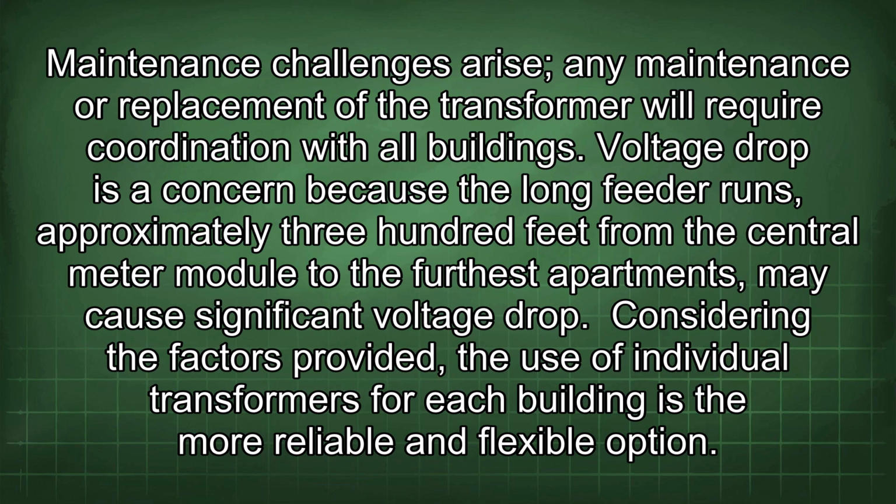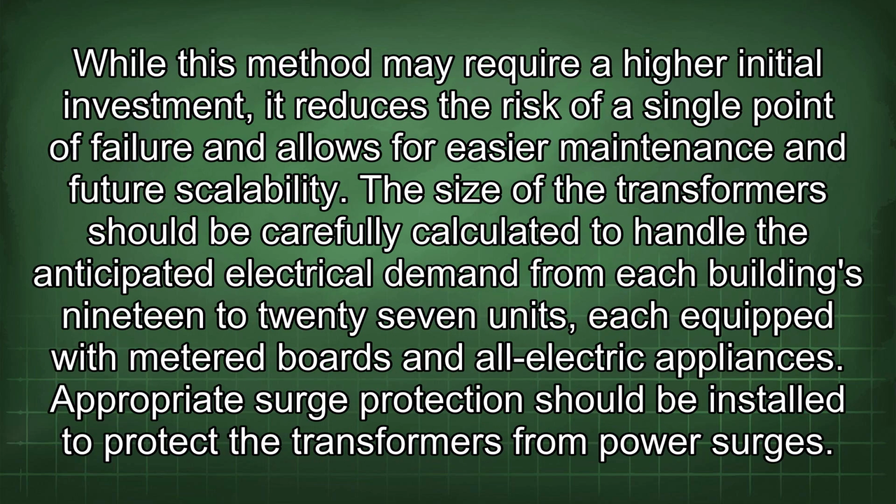Considering the factors provided, the use of individual transformers for each building is the more reliable and flexible option. While this method may require a higher initial investment, it reduces the risk of a single point of failure and allows for easier maintenance and future scalability.